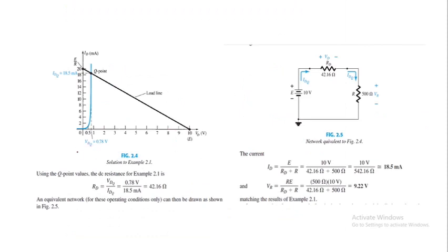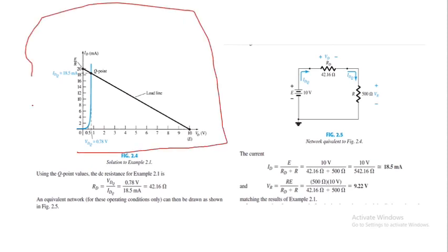Now this is the same figure, with the scale redrawn, and now you can see E is one point, and at 20 milliampere, E by R is another point, and when you connect these 2 points, you are actually drawing the load line and finding the Q point where the intersection of the load line and the characteristic curve is. Finding IDQ by drawing a horizontal line, and a vertical line will give you VDQ.